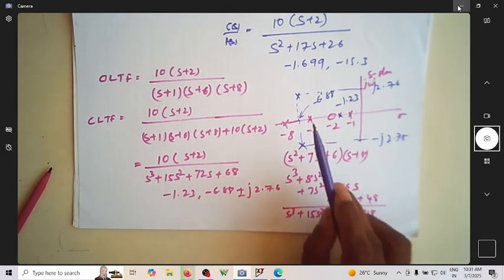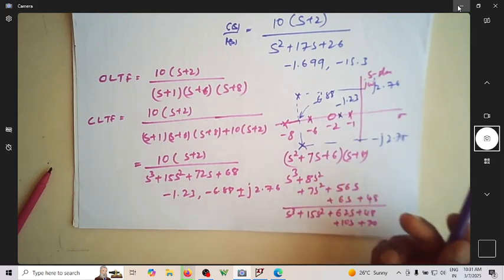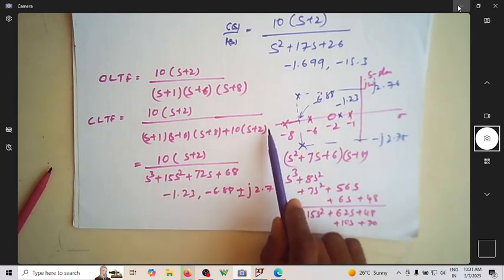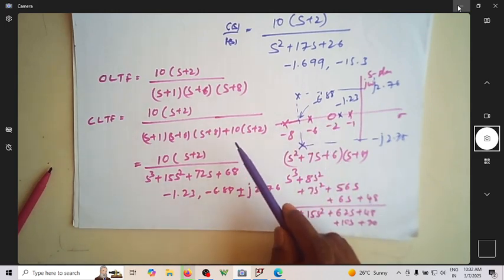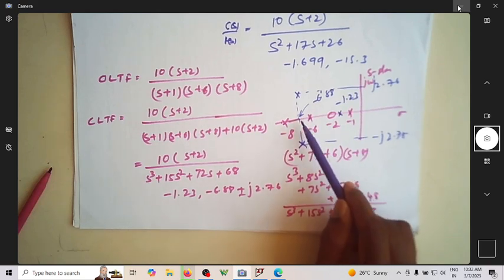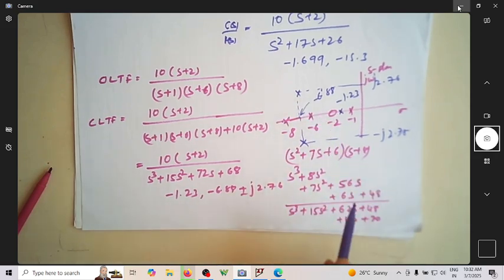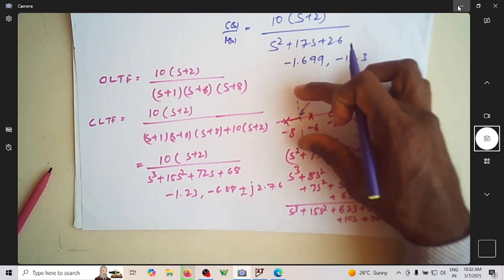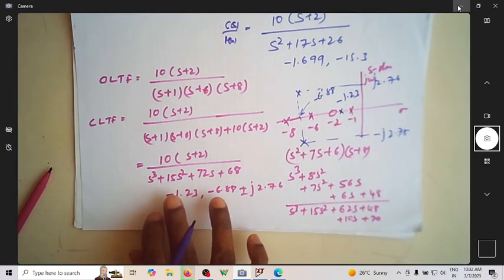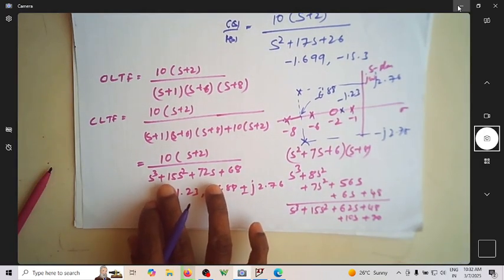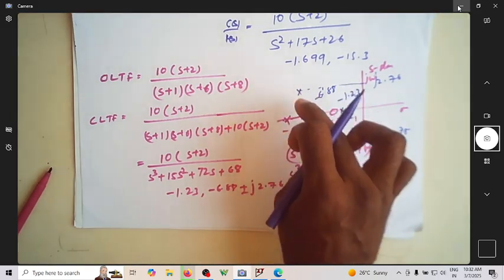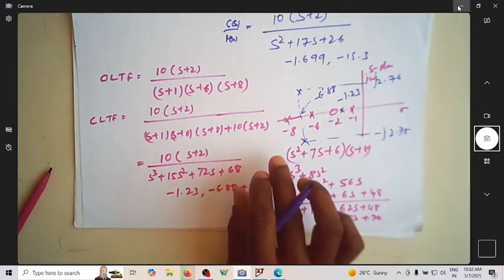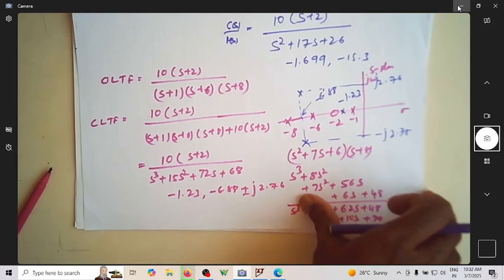It is interesting to see that when you are opening the loop, the poles were on the real axis. The moment you close the loop, these two poles which are on the real axis have now become complex. How do you get to know this? You get to know because of the roots of the poles. The roots will tell you where your closed loop poles are upon closure of the loop.